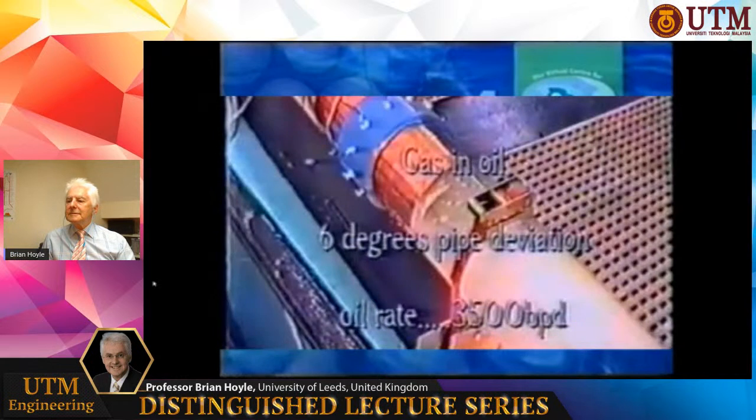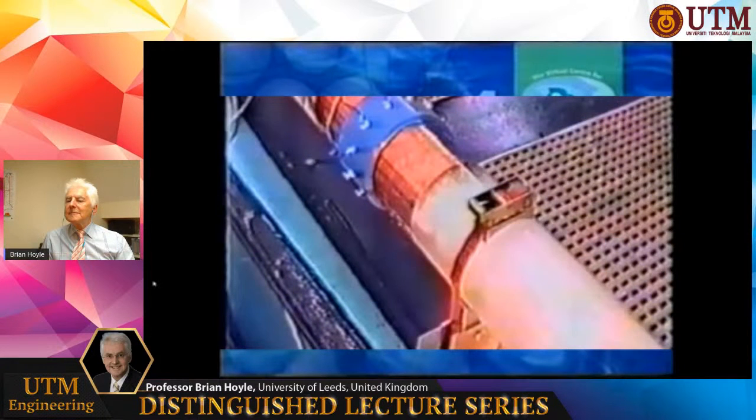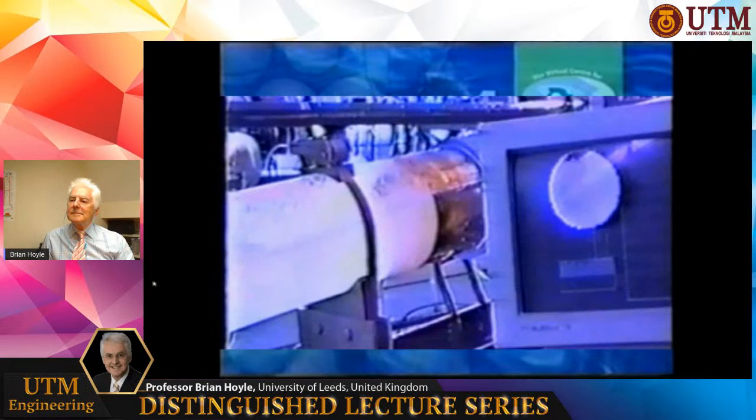The difference in the dielectric properties between the two components allows us to visualize the distribution of the oil and gas phases using a method based on capacitance tomography. This is achieved by placing a number of electrodes, typically 12 or 16. There is a slight processing delay between what's happening in the pipe and what's happening on the screen.